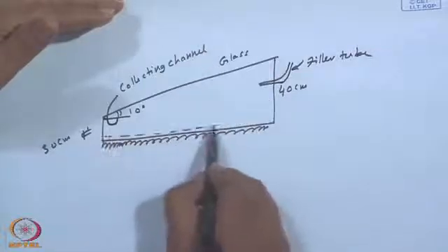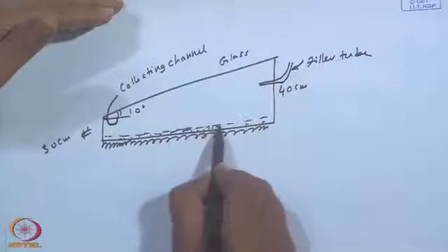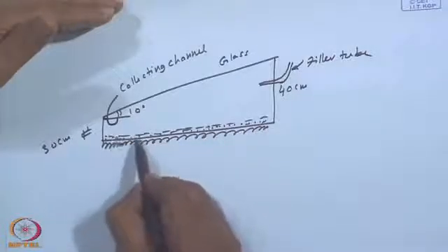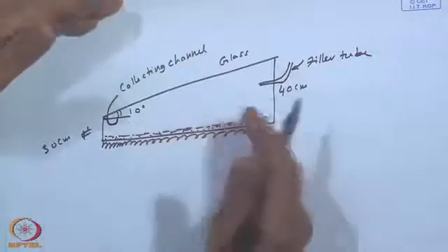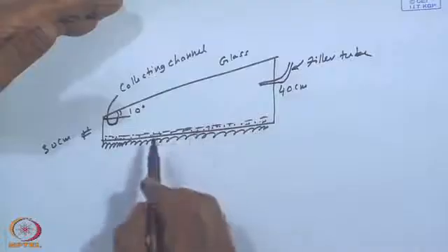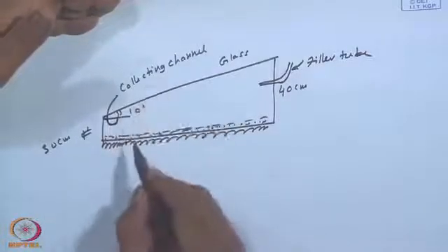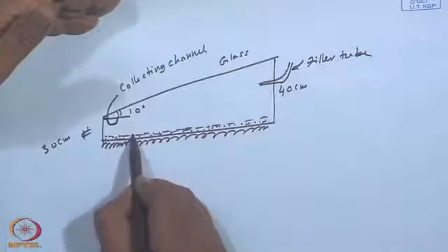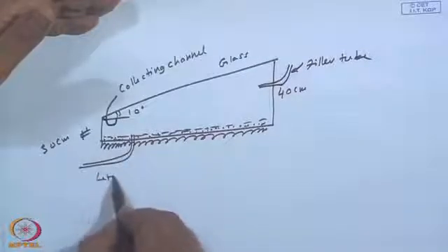You have a layer of water, maybe 2 inches, because if it is too much, the heat capacity will be large, and consequently to heat that much larger quantity of water, it takes more time. At the same time you do not want to have dry patches, and this is the collecting channel which I have mentioned. And if you want to have a control for the level, you can have a drain level control.